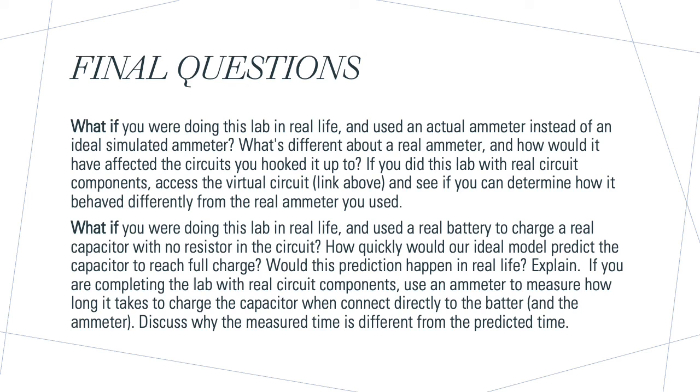And same thing with a real battery, you're going to have some resistance in the battery too. So if you're charging a capacitor with no resistor, it's still going to act like there's a resistor in the circuit just because there is a small resistance in the battery. So this will cause different values, and it really just depends on the materials you're using, because also over time the materials will wear out and they won't be as brand new, while in a virtual experiment it's always going to be exact based off of measurements.